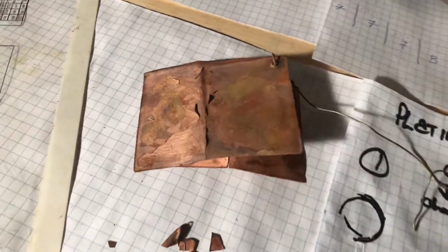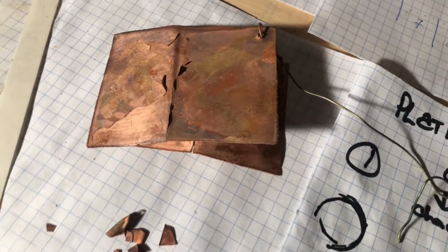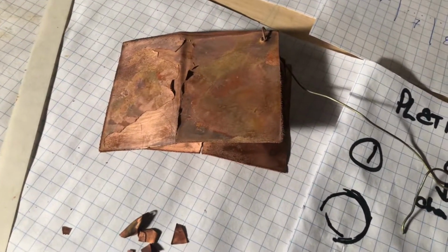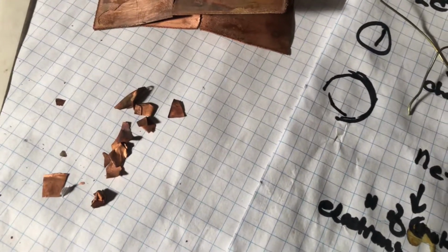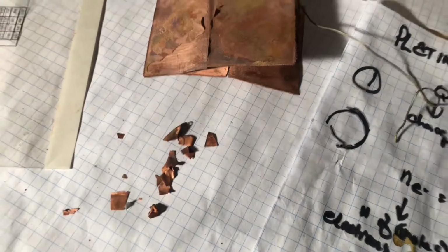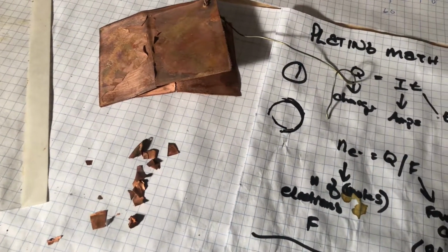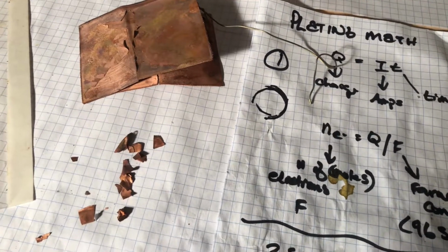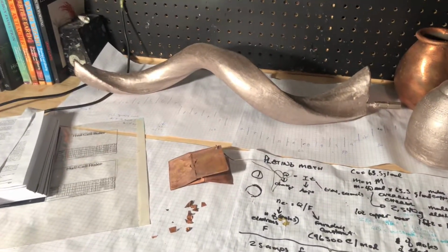This is a small plating test. What I do is I take my solution, drop it into a beaker, plate, peel the copper off, and if the copper has the qualities I'm looking for, ductility, fine grain structure, smoothness, then I'm ready to load the part in the bath. And that's where I am right now.